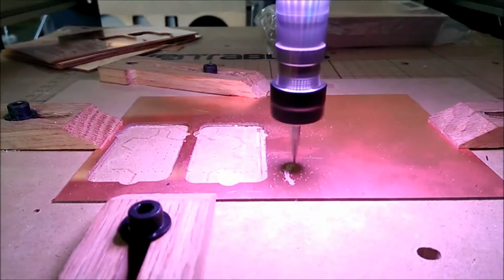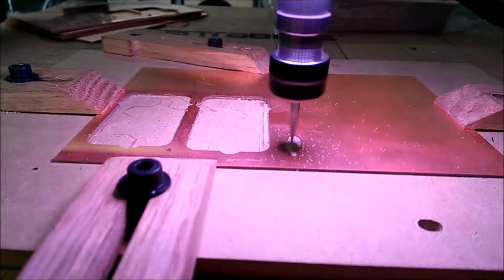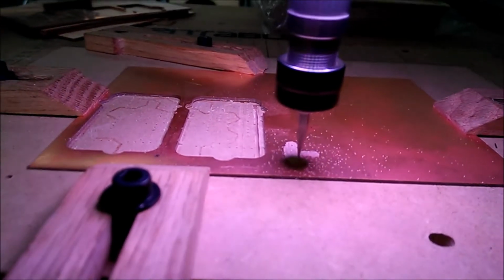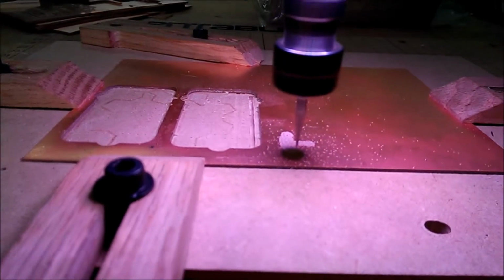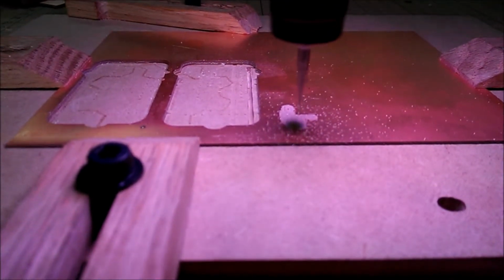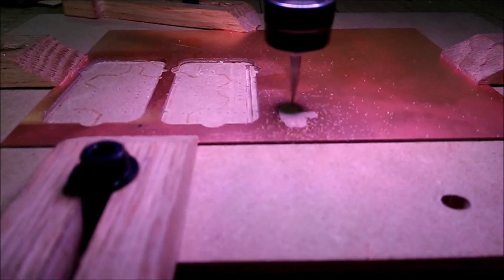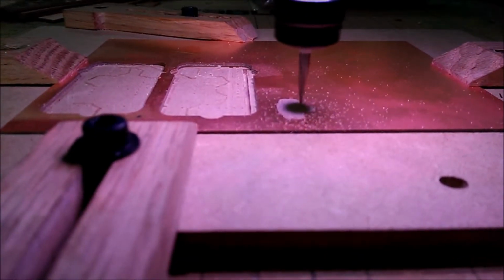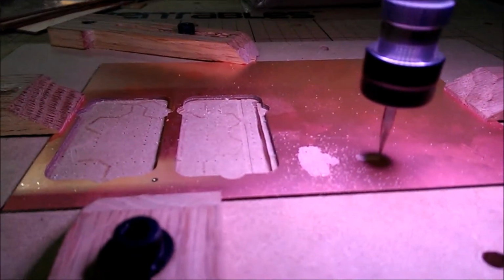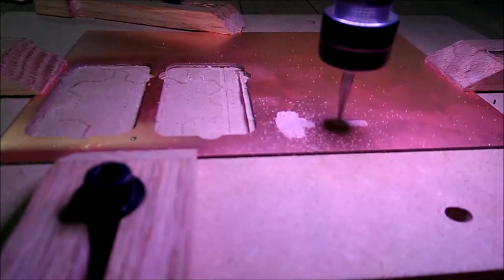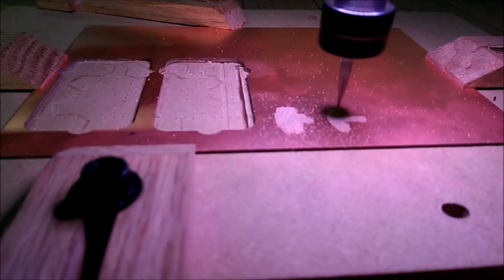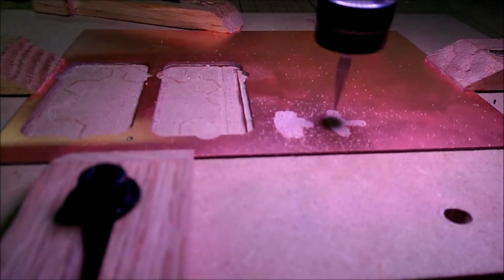So you'll see that white powder that comes up. That's exactly what we want to see. That means that it's getting through the copper and into the board itself. Now this board is not made of glass like a lot of the different types are. If you're doing one that's made of fiberglass, you really want to wear a mask to protect from the dust. This is just paper. It's a paper-based board, so you don't need a mask. It doesn't really kick up a lot of dust. I wouldn't inhale it, but like you can see, it's not really kicking up any dust, so you don't really have to worry about it so much. So I'm going to let that go, and we'll let you have a look at it once we get ready to do the lettering.